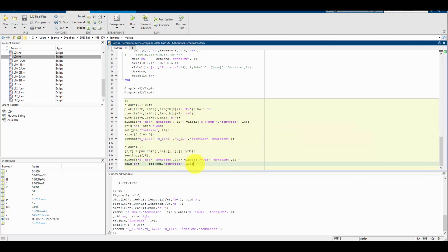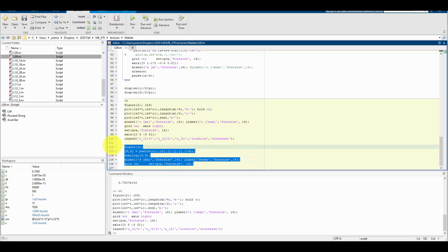And finally, I want to look at the frequency spectrum. I'm going to look at, again, just 1 point, and I want to see in the frequency domain, what is it doing? So for this one, I'm using a little bit better version of a power spectral density function than when we do it by the long way, kind of using fast Fourier transform. I'm going to use pwelch to do this. That's going to use windowing. It's going to give us a little bit better result than the way we typically have been doing it with taking the FFT and then looking at those coefficients. So we get a little bit cleaner of a signal.